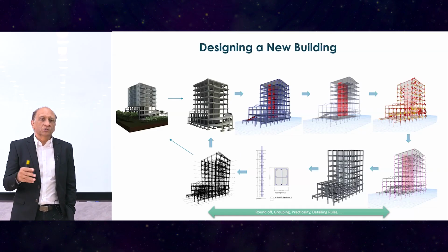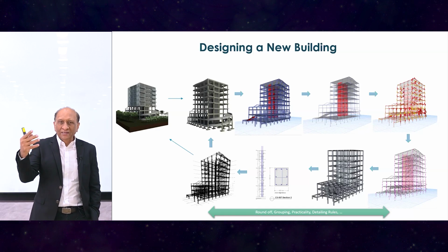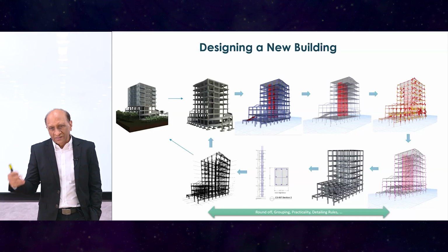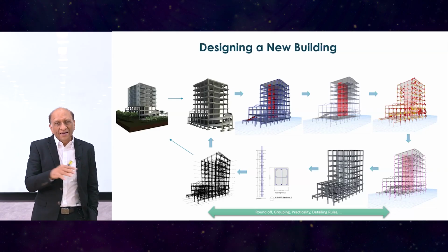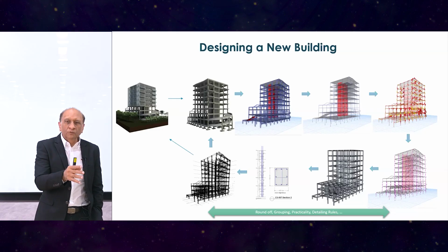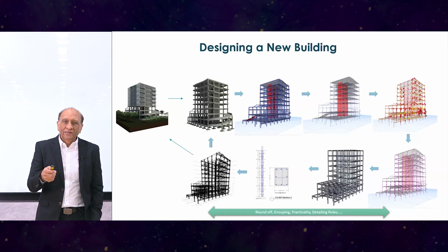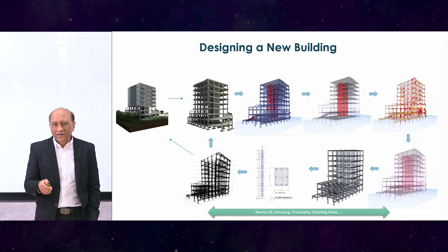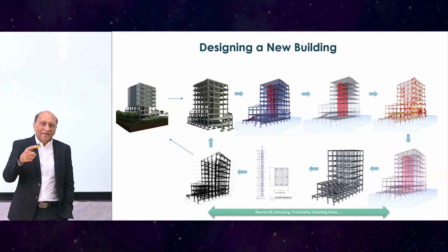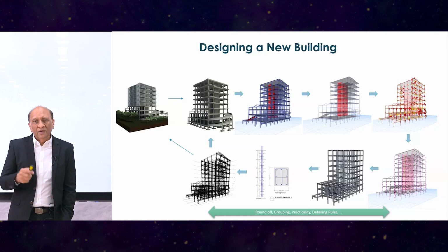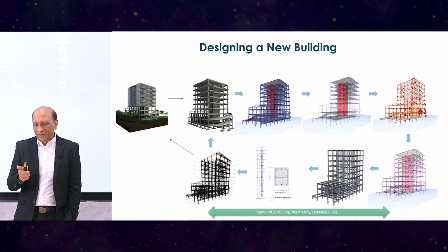So whatever R we use, whatever seismic forces we use, they are correct up to the analysis. But after the analysis, from design to detailing, the results are sort of mixed together, and the final output will not be the same as the analysis would indicate, because analysis would indicate each column at every floor to be different, but detailing will say no, 10 floors are the same, next 10 floors are the same. And that produces a structure which is different from what we designed, and now the behavior of the structure will not be what we started with.